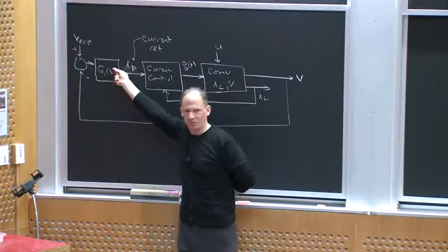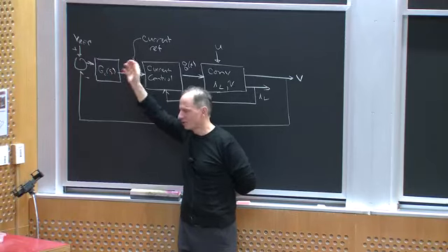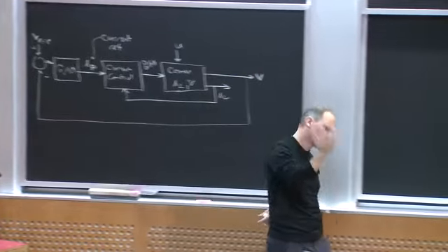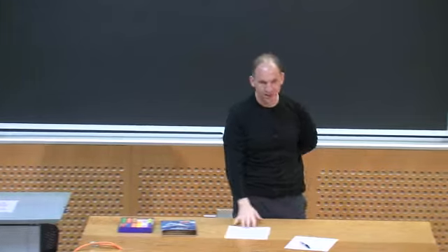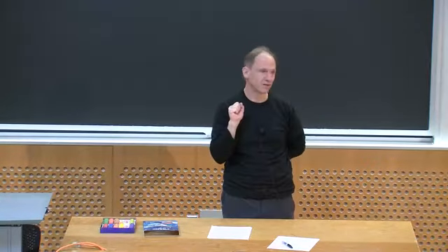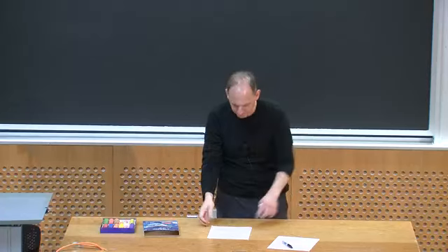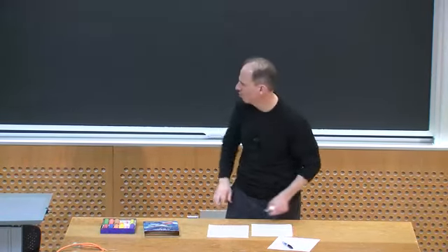So the crudest way people like to think about this is I'm putting the inductor current inside a loop. So now I get a sort of commandable current, and then I sort of have a first order system. Now it's not quite that good. That's an oversimplification. I still have two state variables, it's still a second order system, but it's not a bad way to think about it.